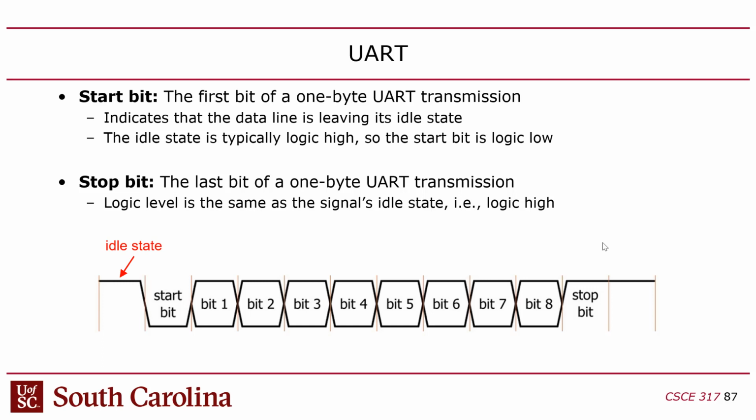Now the problem with that is that you end up having 2 different clocks on either side of the channel, where one is used to generate the data, and the other is used to sample the data. And how do you know that when you're sampling the data, you're not sampling just as the data is changing? In other words, how do you know the data is stable when you sample it? And the answer is you don't.